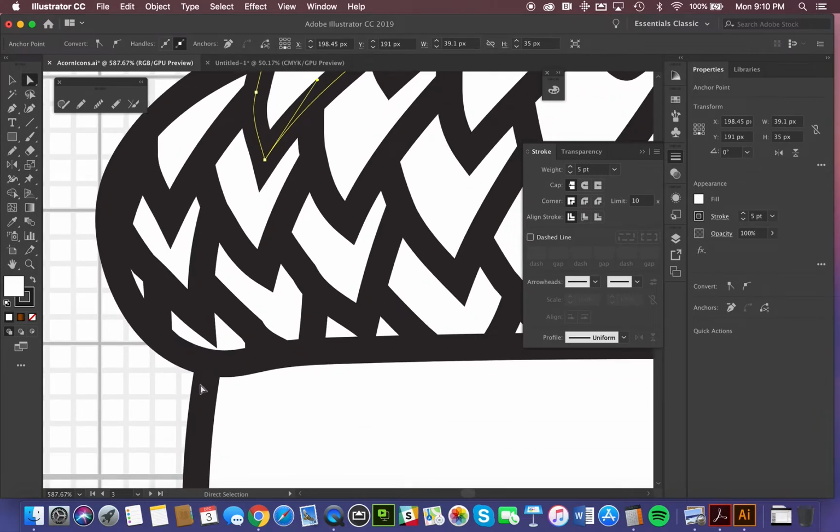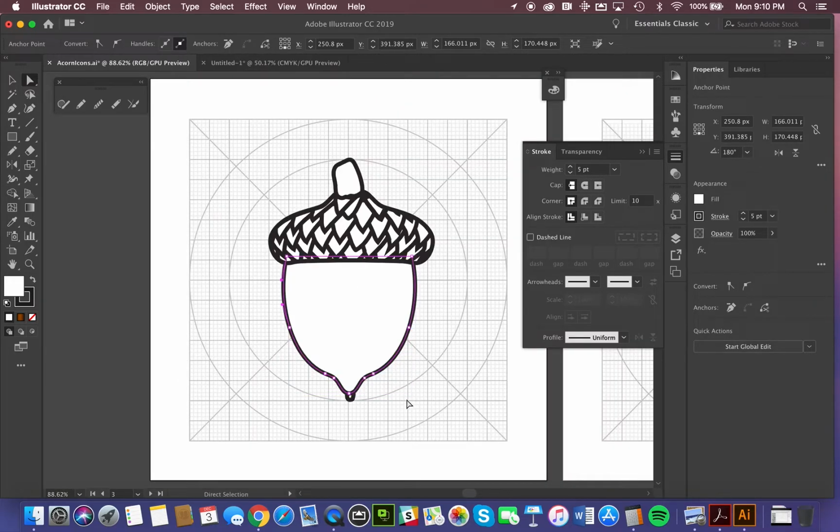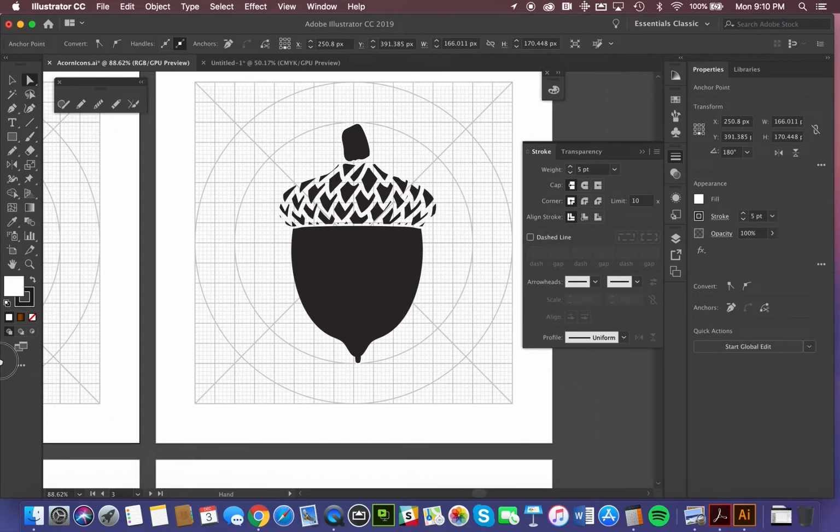So that's why I've made these things this thickness. It has to be a minimum of 1 grid pixel in size. And the reason for that is if things are any smaller than that 1 pixel minimum, then they might cease to even be represented when they're brought onto a handheld screen. The line work would just simply not be rendered. So we have to be mindful of that. And I'll just zoom out for a sec and move along to the next example.